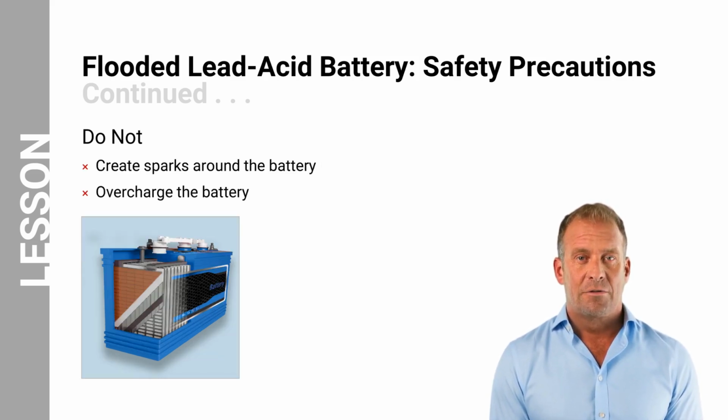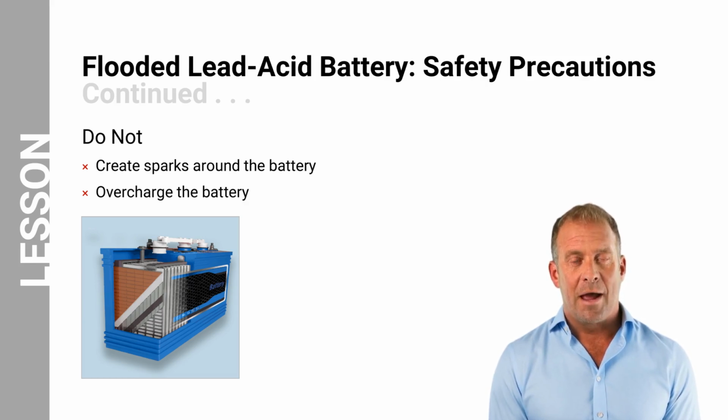Let us now look at the do-nots. Do not create sparks near the battery, especially during charging. Avoid overcharging the battery and reduce the charging rate if the case gets too hot.